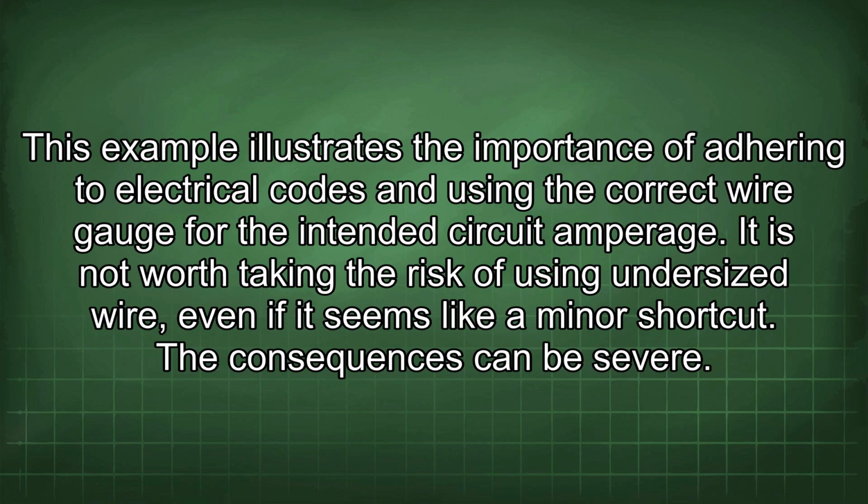This example illustrates the importance of adhering to electrical codes and using the correct wire gauge for the intended circuit amperage. It is not worth taking the risk of using undersized wire, even if it seems like a minor shortcut. The consequences can be severe.